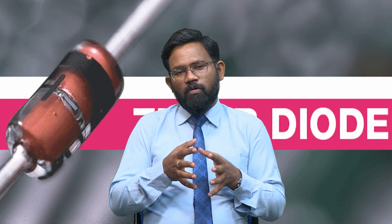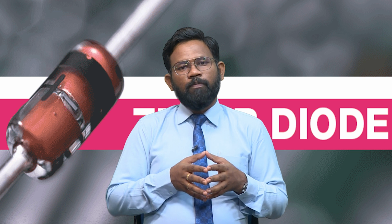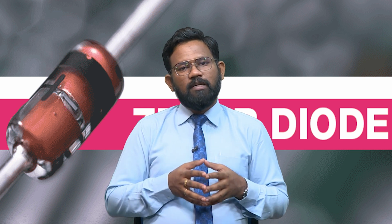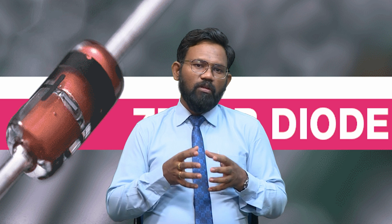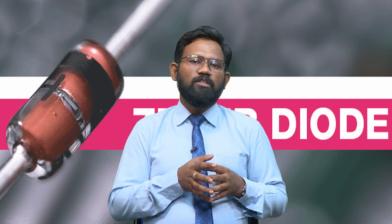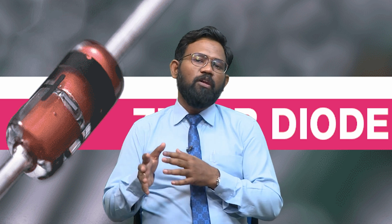So, this is how the voltage is regulated in small rated loads using the Zener diode. The breakdown voltage of Zener diodes will be constant for a wide range of currents. That is why Zener diodes are used for voltage regulation, since the breakdown voltage of a Zener diode will remain constant for different values of current.